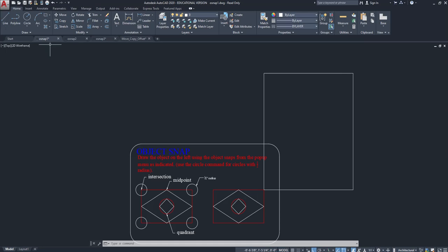So I use the line command and all these drawing tools to draw things. I input, right, numbers or dimensions to make them dimensional, and then I measure them to make sure they're correct, okay? So there's a couple of different ways that we can measure things here in AutoCAD. The command at the command line is DIST, distance, okay? DIST. These commands, you'll notice, they shortcut. You get sort of an auto prediction happening down here at the bottom of my screen. So with distance just typed, I could hit enter, or I could click on one of these. Click, and it initiates the command, okay?